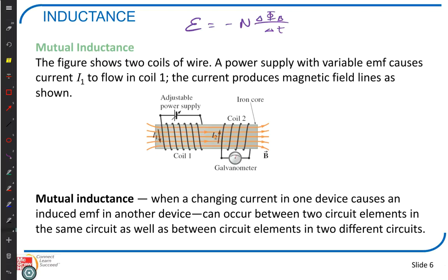When you actually have magnets and you store magnets, ideally, because magnetic fields do a loop, if you have iron material connecting from the North Pole to the South Pole, then the iron material will make it so the magnetic fields can stay within iron, much stronger magnetic field, and do the loop, and you have less stray magnetism. It's going to keep it aligned better, so it'll keep your strength of your magnet better. So this is keeping it so any magnetic field that goes through coil 1 goes through coil 2. So that's the purpose of having that.